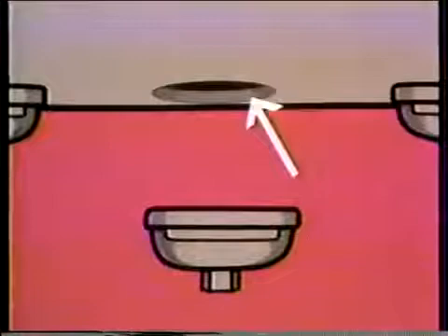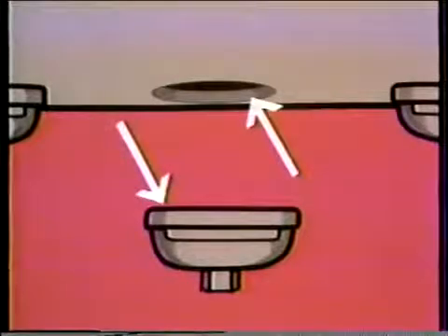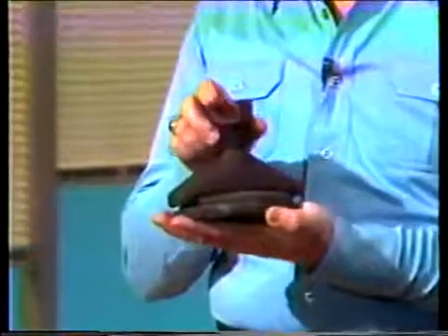Handhole sealing surfaces should be examined for surface irregularities. Irregularities can be caused by steam erosion, which is the result of leakage. The handhole sealing surfaces should be thoroughly cleaned before you inspect them so that you can see the surfaces clearly. Be sure to look at both the sealing surfaces on the header as well as the sealing surfaces on the handhole plate. Also, check the handhole plate for warping. Now, warping might cause leaks.